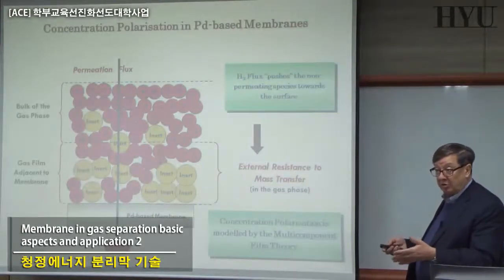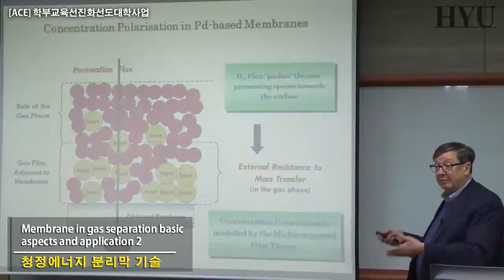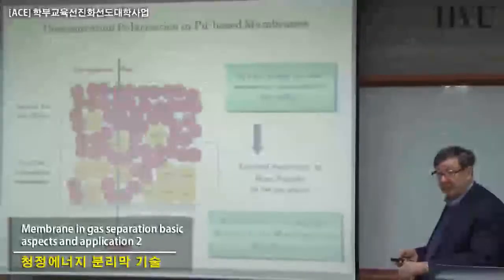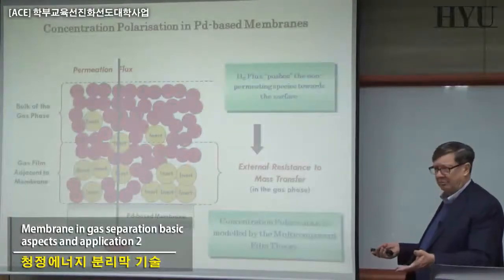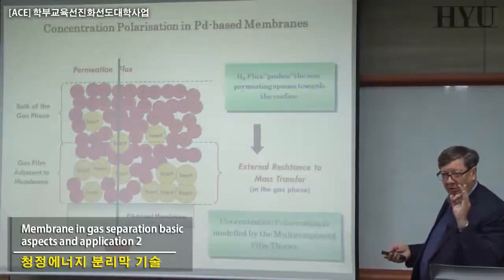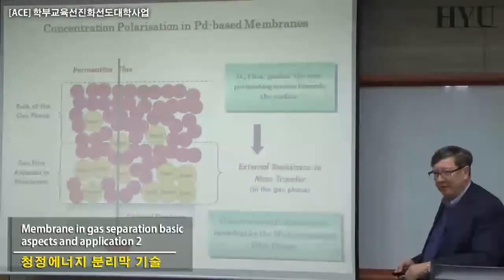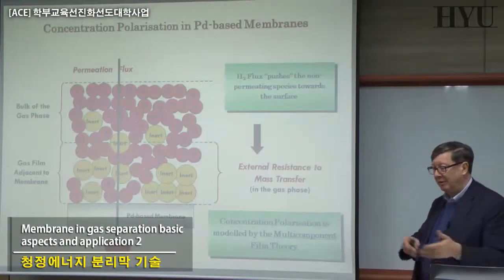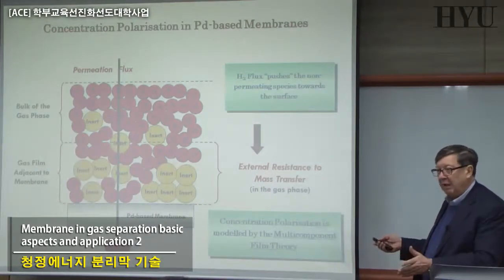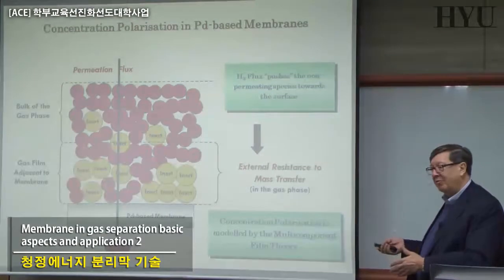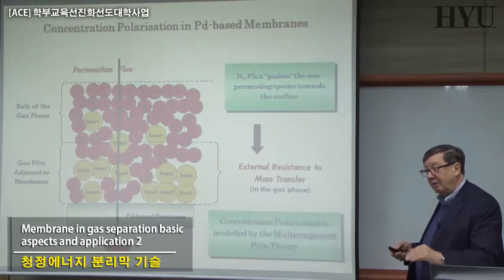You can have a situation in which the membrane is perfect, but if you have seawater as a feed, you can check what is going through and you see seawater. So you say, this membrane is broken. There's a big hole, and what I put in the feed is now going to the permeate. And you change the membranes. That means you lose 30%, 20% of your investment. Nothing to do with the membrane. The membrane is still perfect. But you can have this result if you don't control carefully the interfacial phenomena.